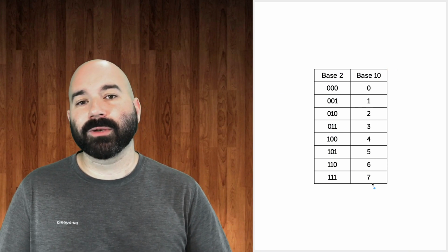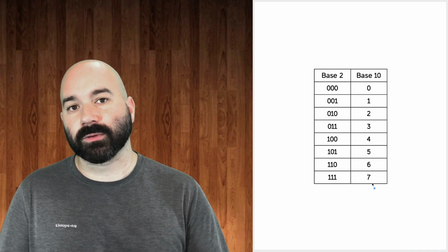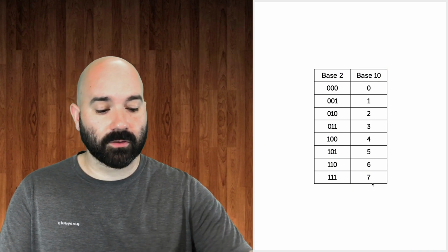We have to know how many samples of audio we should take for those data points to also accurately represent it. And that'll move us over to the Nyquist theorem, which simply states that if we want to record a frequency of 20,000 hertz, then we need a sample rate of at least 40,000 hertz. So if we want to record 20 kilohertz, then we need to sample at 40 kilohertz. And if we don't do that, then we're not going to be able to capture those frequencies.